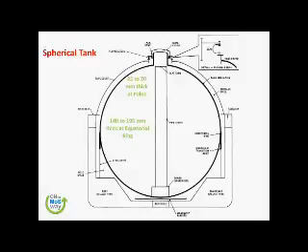Now, because you are working on a spherical model, you can see these are the 35-70 millimeter thick shells. But did you notice your tank becomes thicker and thicker when it comes to the equatorial ring? Mind that this is the equatorial ring where the tank is sitting in the socket.